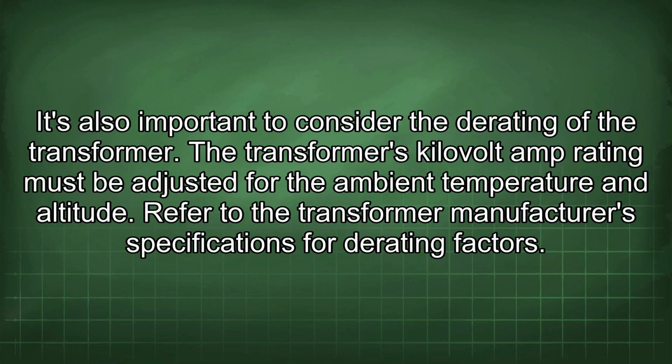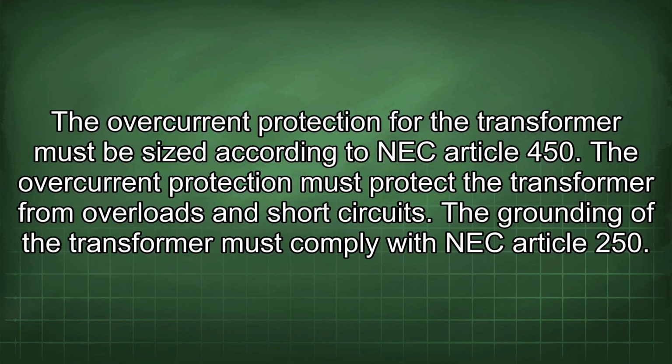It's also important to consider the rating of the transformer. The transformer's kilovolt amp rating must be adjusted for the ambient temperature and altitude. Refer to the transformer manufacturer's specifications for rating factors. The overcurrent protection for the transformer must be sized according to NEC Article 450. The overcurrent protection must protect the transformer from overloads and short circuits.